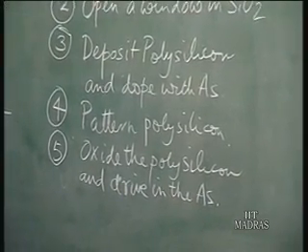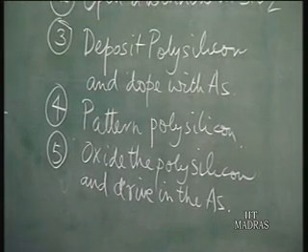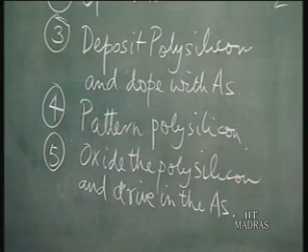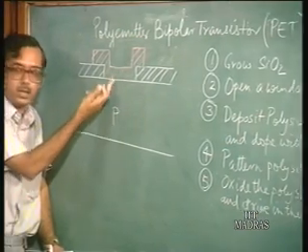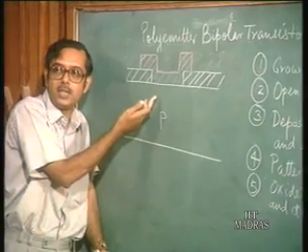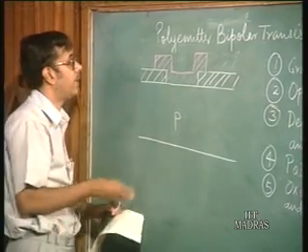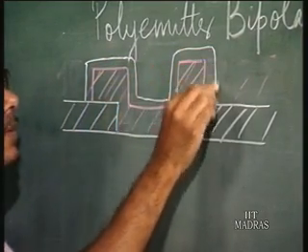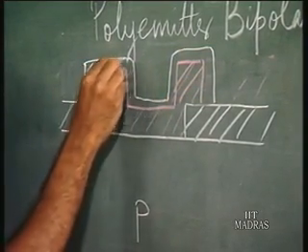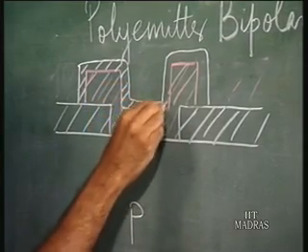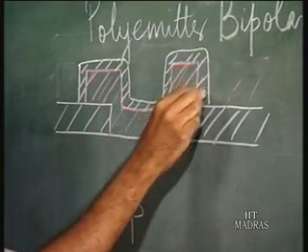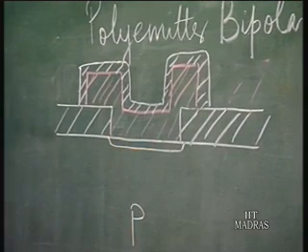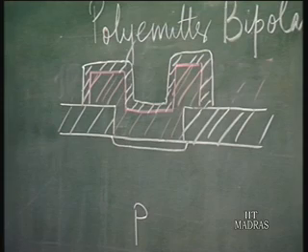Oxidation of polysilicon is a high temperature process. Okay. And as you oxidize the polysilicon, what happens is the arsenic impurities in polysilicon also go into the silicon. They diffuse into the silicon. And so, what you have is another oxide layer on polysilicon, since you have oxidized it. And simultaneously you form an NP junction here. Okay. This PN junction is formed.